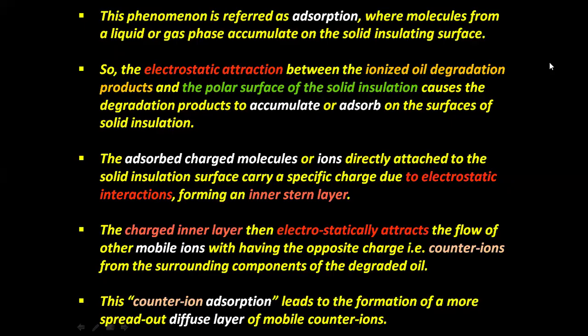The adsorbed charged molecules or ions directly attached to the solid insulation surface carry a specific charge due to electrostatic interactions, forming an inner Stern layer, that is a compact layer.